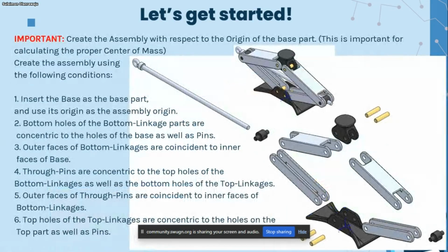Create the assembly with respect to the origin of the base part. What is the base part? The base part is the first part you import into the assembly environment. As I said here, this is important for calculating the proper center of mass. The question now goes thus: create the assembly using the following conditions. Insert the base as the base part.